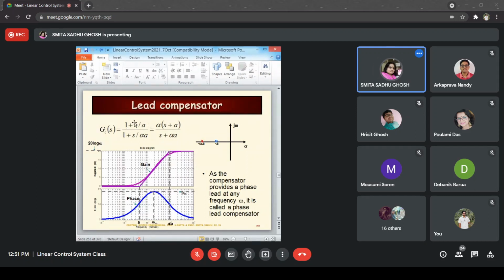So the first step in drawing a Bode plot would be, if you have the transfer function given in the pole-zero form like this one, you would have to convert it into the time constant form. If it is given in the time constant form, you can use that directly. So the first step would be to identify the corner frequencies. Here, say the numerator is in the form of 1 plus s tau 1, right?